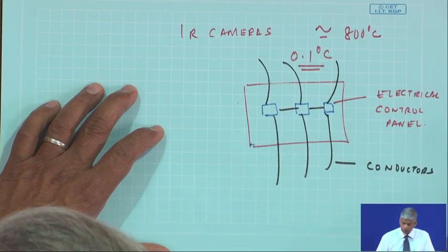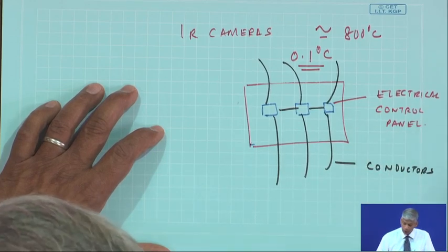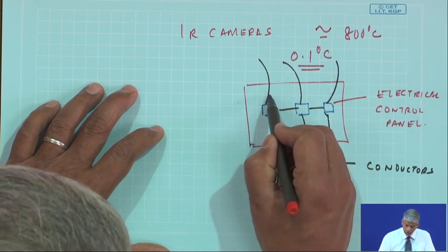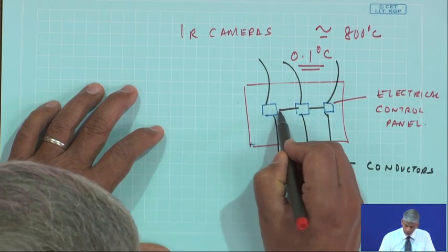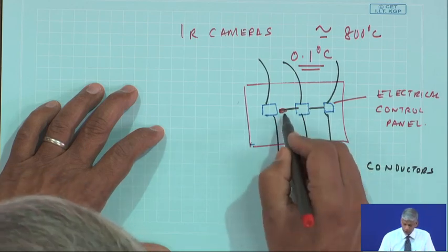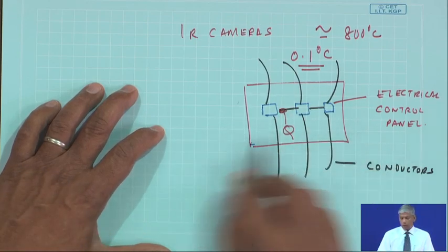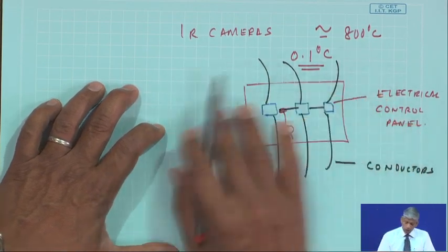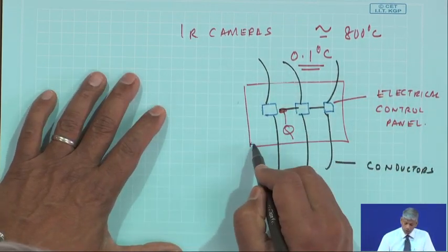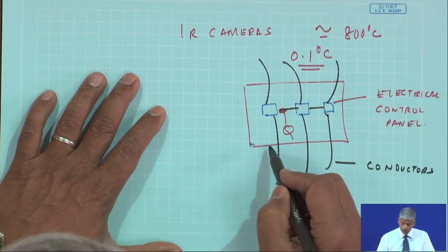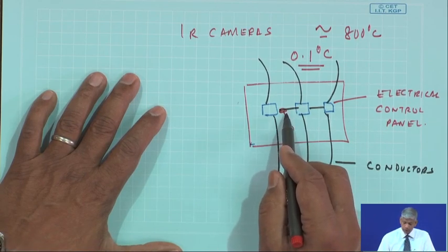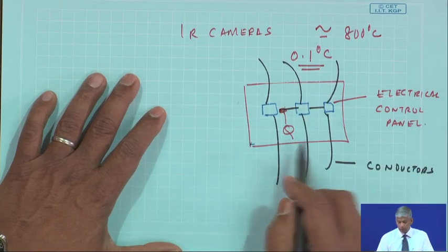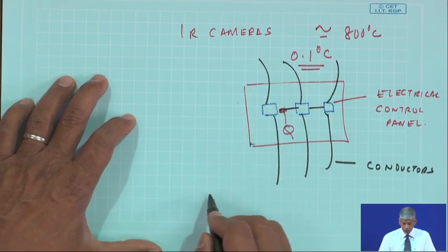Okay. So, what can happen is you can always take a thermal image, and suppose there is some short circuit or some loose connections. So, a lot of heat generation is there. So, by doing a quick thermal imaging scanning of the surface, you can find out what the temperature of this area is and where the short circuit is. Then later on you can do a diagnostic to find out why that short circuit happened.